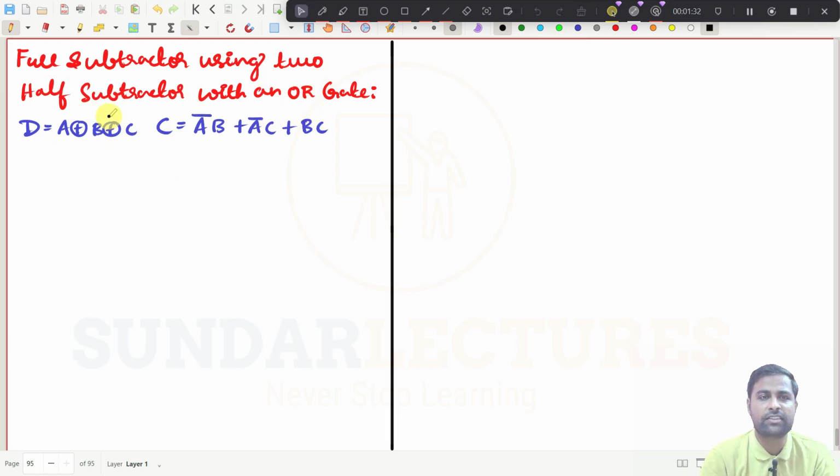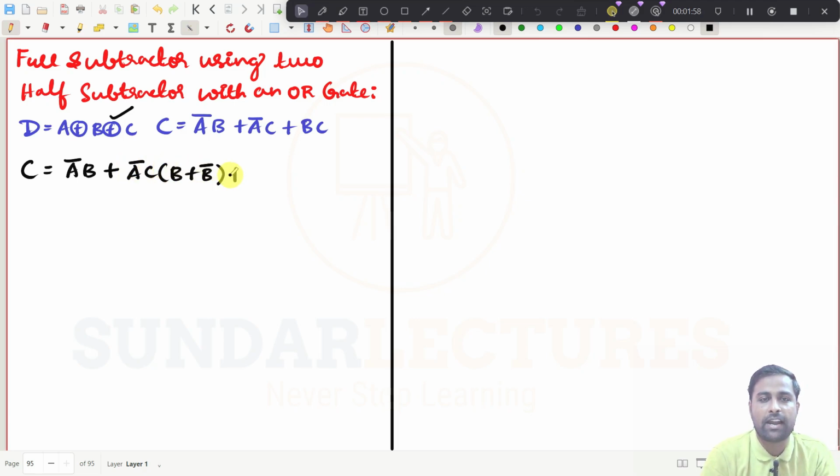So now difference is no problem. I have already told you, like adder, but the carry you have to rearrange this equation. So what we can do now, from this, you just write this A bar B. You don't do anything with A bar B because we already have A bar B, right? You can see the half adder now. In half adder, this A bar B is already there, so you don't do anything with that. And for this one now, A bar C, put B plus B bar here. And for this one BC, you put A plus A bar, right?